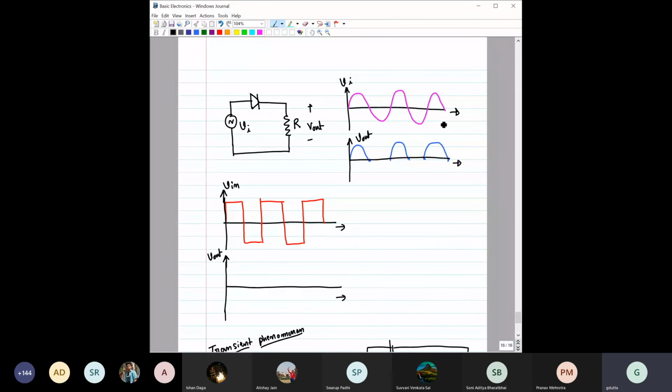I think, sir, if the temperature is higher, if the doping is higher, then Zener breakdown will occur before avalanche breakdown. Yes, for Zener breakdown, we intentionally make the doping concentration so high that the mechanism of this breakdown is primarily due to tunneling, and the breakdown voltage is usually between 5 to 12 volts depending on the design. And sir, what is the range of avalanche breakdown voltage? In some cases, it may be more than 200, 300, even 1000. You can design it. It also depends on the design.